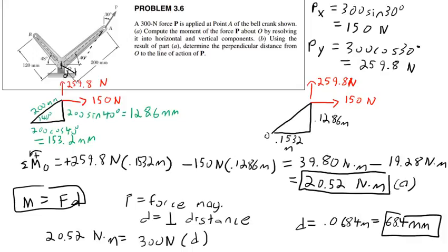Okay. All right. Again, the distance is perpendicular, but not the force. Yes, in this case, the distance would be perpendicular. Well, actually, if we drag this force all the way back along here, if we move this force vector all the way back here, the force actually would be perpendicular, yes. Remember, we can move a force anywhere along its line of action and it won't change the result?